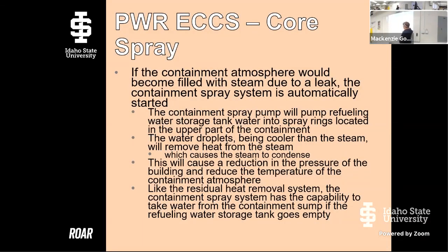If the atmosphere inside containment would be filled with steam, and we're starting to pressurize containment, this is one of the things that happened at Fukushima, and we had these hydrogen conflagrations that blew the top off the containment buildings, right? They're little square buildings. By spraying water into that gas that's creating the pressure, it can then be condensed, right? You're putting cold water in contact with hot steam, you condense it down to a liquid, and then you reduce pressure, right? So this system is designed to prevent that kind of issue that they had at Fukushima, okay?